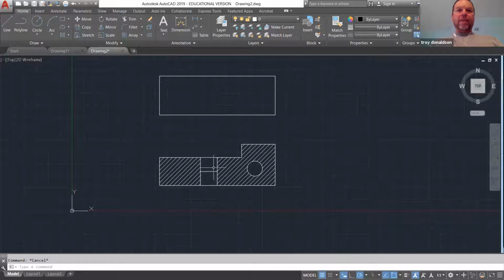That could be this. Drag that up and then say circle, and try to drag this out, see if it'll let me. Yeah, it did. So that circle is the same size as that hole. Get used to those marching eights, and it's okay that it's off because I'm going to put my cutting plane right through it. And for it to show up as a hole, it goes through it this way. So it must have some kind of, hopefully it'll make sense. Now these would need to be hidden.